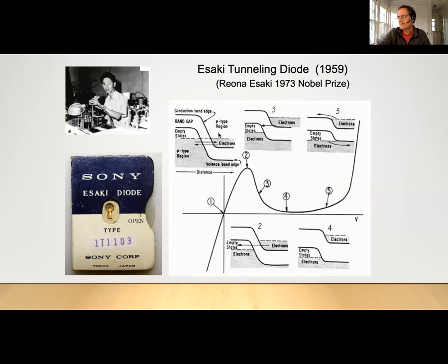Okay, and this is a tunneling process. I don't want to go into the details. It's a little complicated because we have electrons that tunnel from an N-type material to a P-type material in a p-n junction. But the idea is that we get this pattern in the tunneling rate, and it shows up in the current voltage characteristic of the device, because the current is proportional to the transmission probability, of course, and the energy of the electrons is proportional to their voltage.